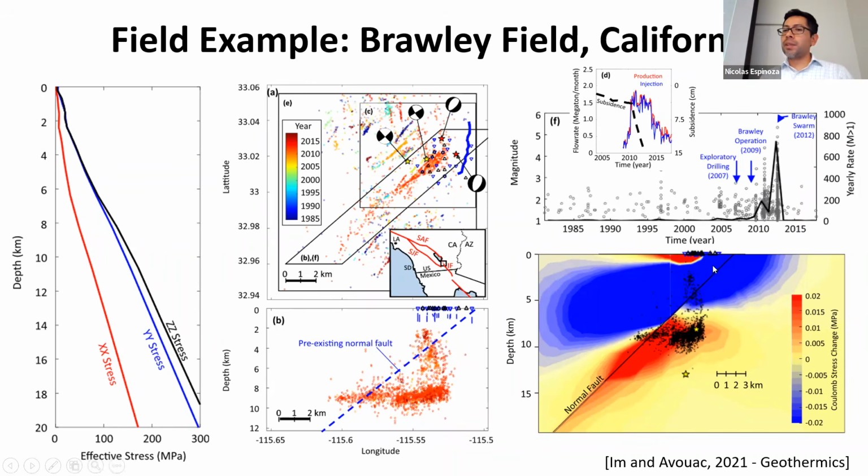In this case, the thermal destressing, seen here in blue, is lowering the stress on the fault, so that if you have less effective normal stress acting on the fault, you're going to have less strength in the fault because this is proportional to the friction coefficient, right? The more stress you have in the fault, normal effective stress, the more shear the fault can take. Now, if you lower that stress, the fault is going to take less shear.